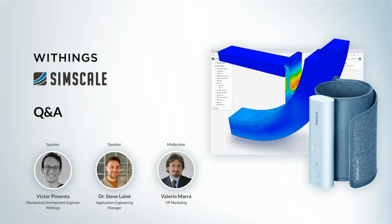Oh, that's a great question. First of all, we had to define a prediction for this coefficient. It's about 5 to 50 times the Young modulus as a rule of thumb. But what we need to know is that the bigger this value is, the harder the contact is. So it really avoids the overlapping of the plastic casing and the electronic board. And in this case it was very important for our design, for our project prototyping, because that's where simulation is powerful. We could predict the design performance ahead of production.